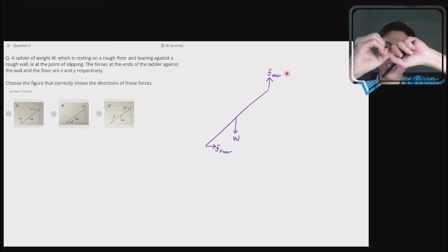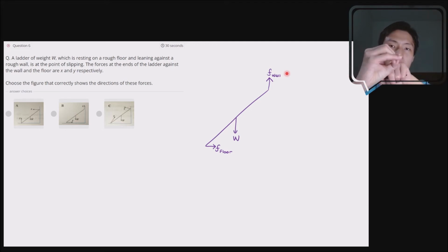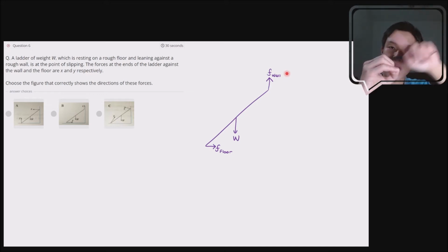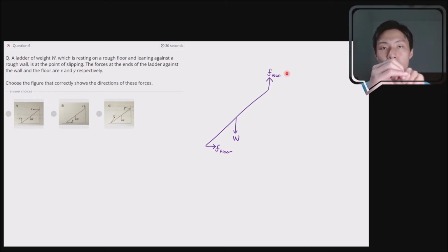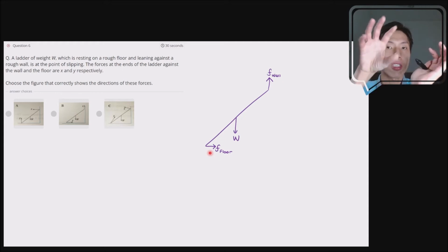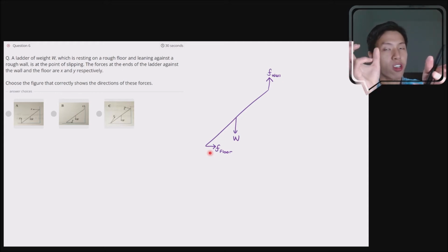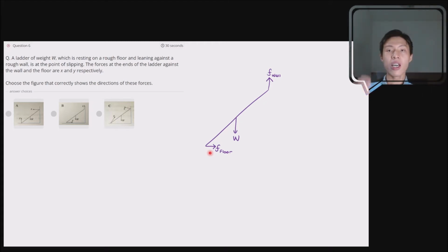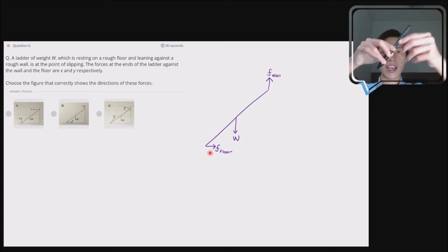Okay, sometimes if it's a hinge, right, a hinge is a complicated structure, then there will be normal force pointing in very complicated direction, and there will be friction pointing in very complicated direction. So if we choose to neglect those complications, we can just combine the friction and the normal force and call it reaction force. But now in this situation here, we have already correctly identified the frictional force. That means we don't have to look at everything about reaction force. We say reaction force is made of friction and normal force. We have determined the friction. That means now we determine only the normal force. That will be enough.